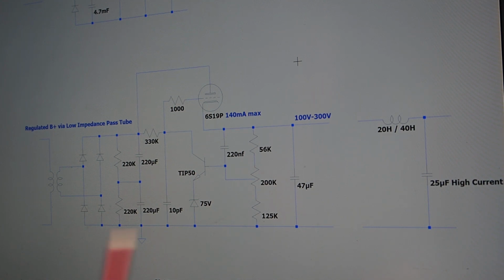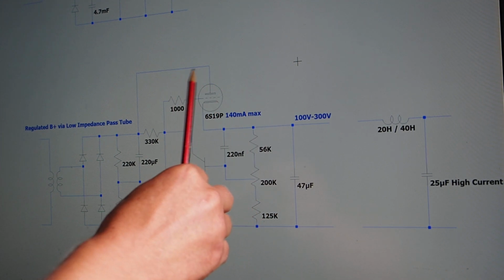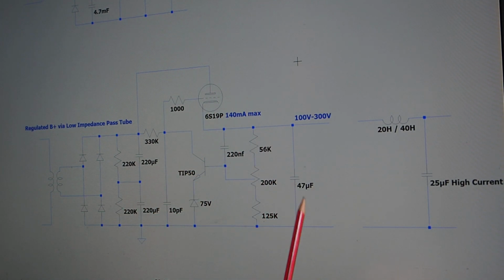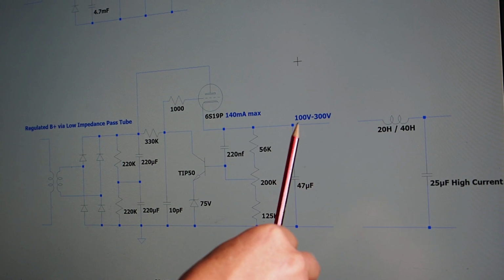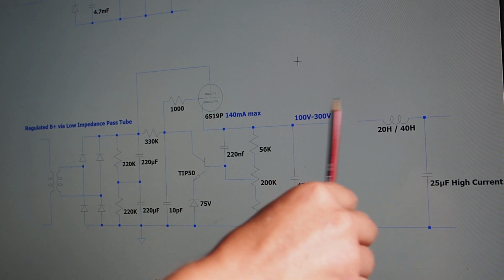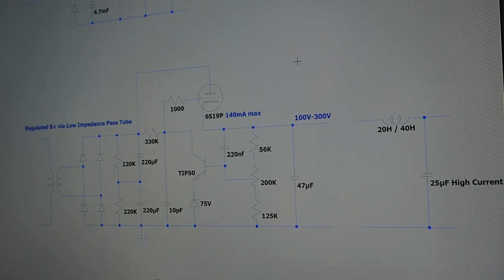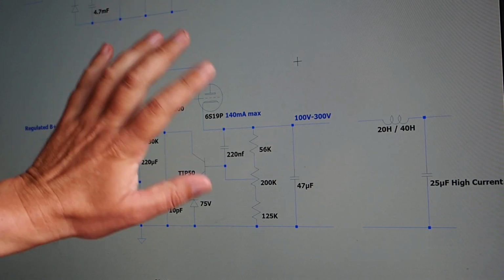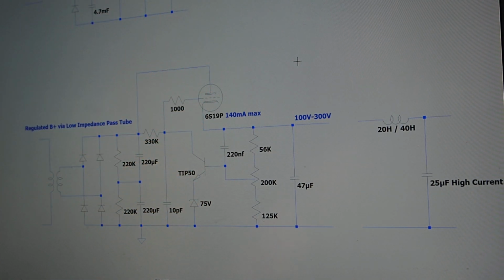And the other thing is, of course, even after this circuitry, even with this cap flattening things out, this is still not usable. You still need to use at least one RC filter after it if you have a single-ended stage there. And that starts to become, for me, an acceptable level of sound quality. So that's the limits. However, as I said, when applied as I have applied it, this works well. You get the positives and very little of the negatives.